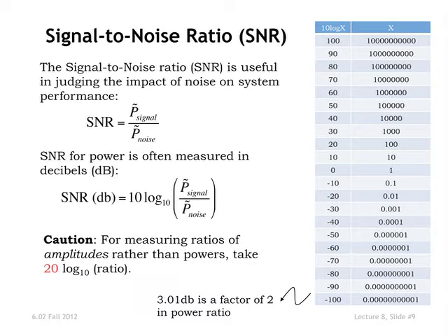Okay. So you can actually span huge ratios in power on this log scale with much better behaved numbers. 0 dB then is a ratio of 1. 3 dB, this is good to carry around in your head. 3 dB is actually 3.01 something, but 3 dB is a factor of 2 on the power ratio, or square root of 2 on an amplitude ratio.